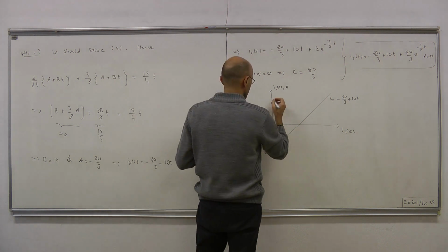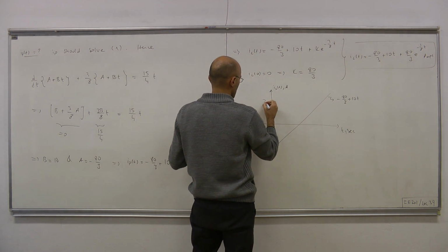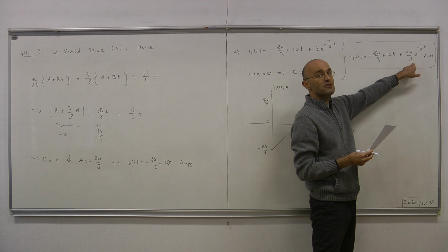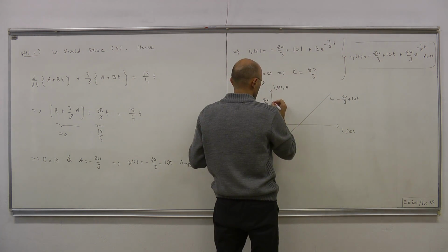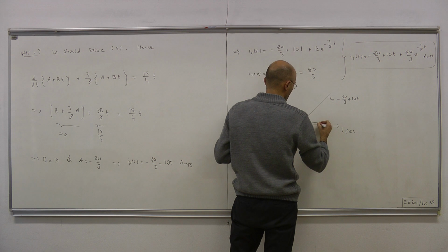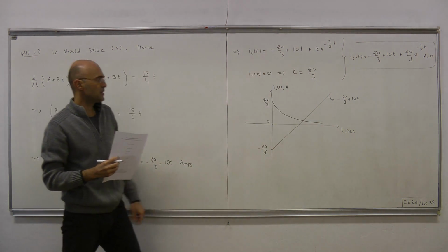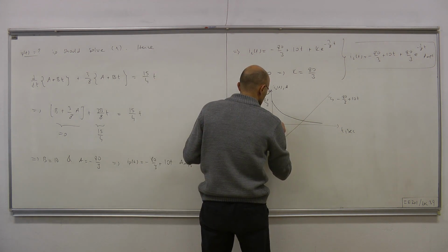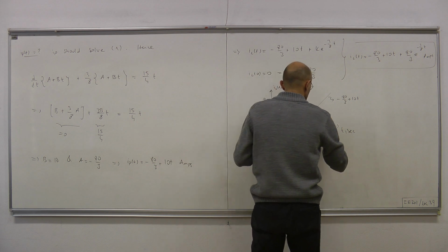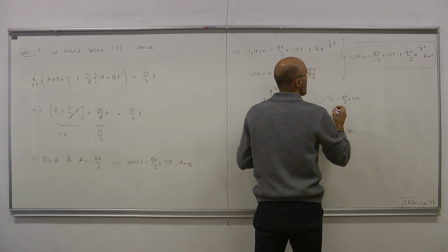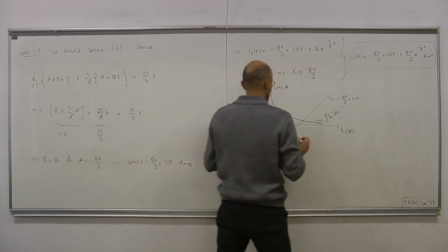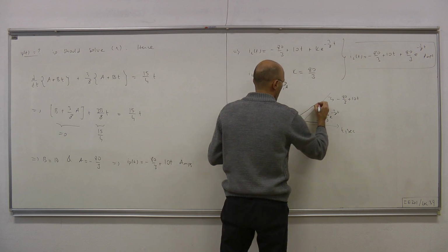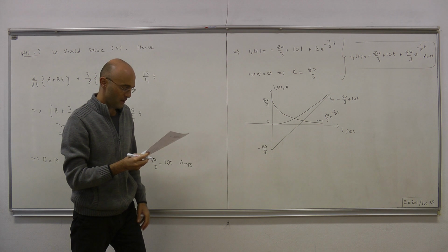And then we have the decaying piece, the homogeneous solution, starting from 80 over 3, decaying towards 0, and the overall solution is the sum of these two curves, which looks something like this. This is 80 over 3 e to the minus 3/8 t, and the sum of those two curves is something like that. This is our i_L(t).